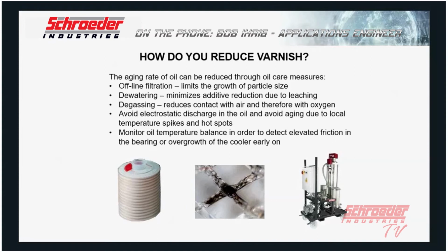Dewatering, of course, as I mentioned early on, hydrolysis is a cause or a potential source of premature or accelerated oil aging, as well as degassing, or removing air contamination from a system, and therefore reducing oxidation of the fluid. Those are all preventative measures, if you will, to minimize the generation of oil degradation byproducts.